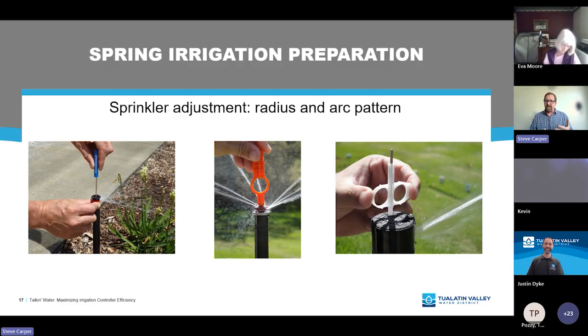But if it seems like it's brittle and you're having to fix it, if it's not standing out, the other thing you might, if you're experiencing that, making sure that you've got appropriate pressure reduction on a drip zone. Drip equipment is meant to operate at a much lower pressure than most traditional pop-up spray type sprinklers.